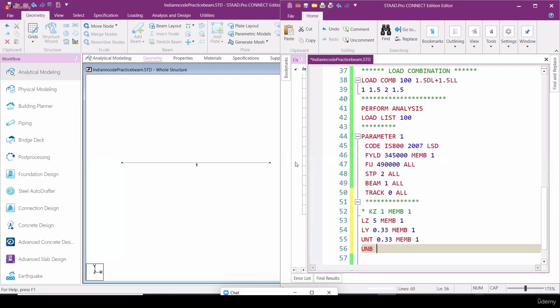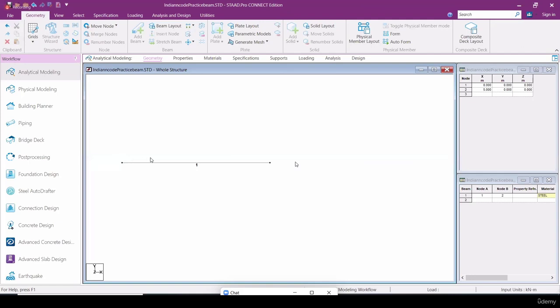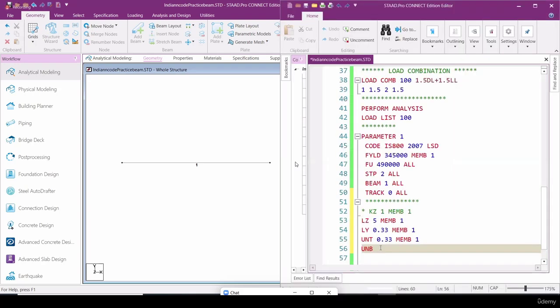For the bottom flange also the same thing? Because I told you yesterday, only the sheeting will be connected to the top flange. If you click the cross section, suppose the I section will be like this. Sheeting will be connected to the top flange only. It will not come up to the bottom flange, right? So we cannot give any support to the bottom flange. So if there is no support, what is the effective length, the unbraced length for the bottom flange? That will be the full length.